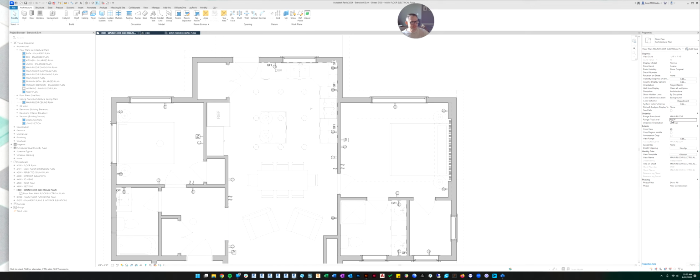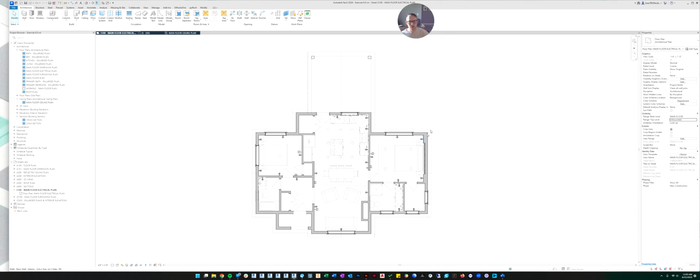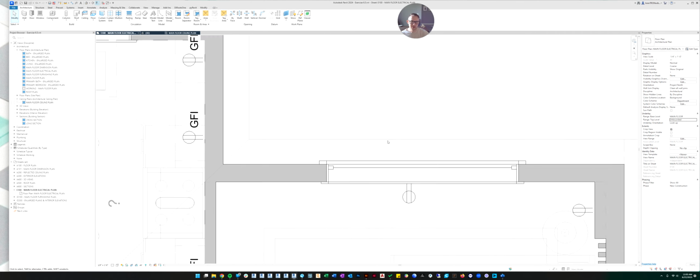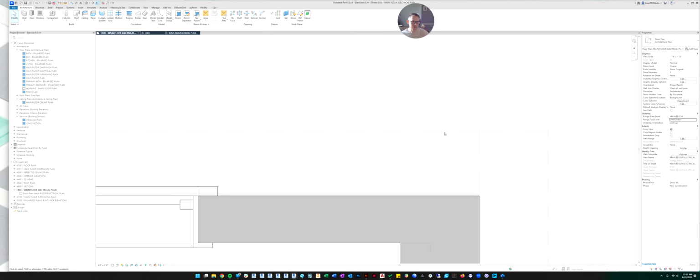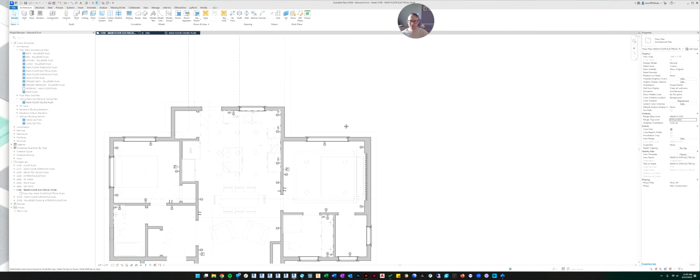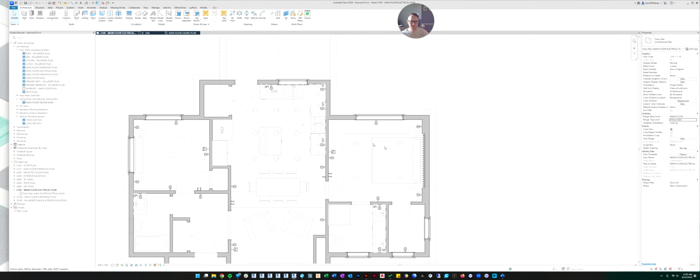It doesn't have an offset value, or otherwise I would just tell it to offset a little bit. But what I have to do is send it unbounded, meaning there's no top. It'll just go forever. And then when I do that, you can see the lights come in. Now there's other issues that it creates, which I don't love, but I'm kind of stuck with. And that's the fact that it's also now trying to show the roof edge in addition to my soffit. So sometimes when you zoom in, sometimes this is a solid line and sometimes it's a dotted line because my soffits are conflicting with my roof, which is frustrating.